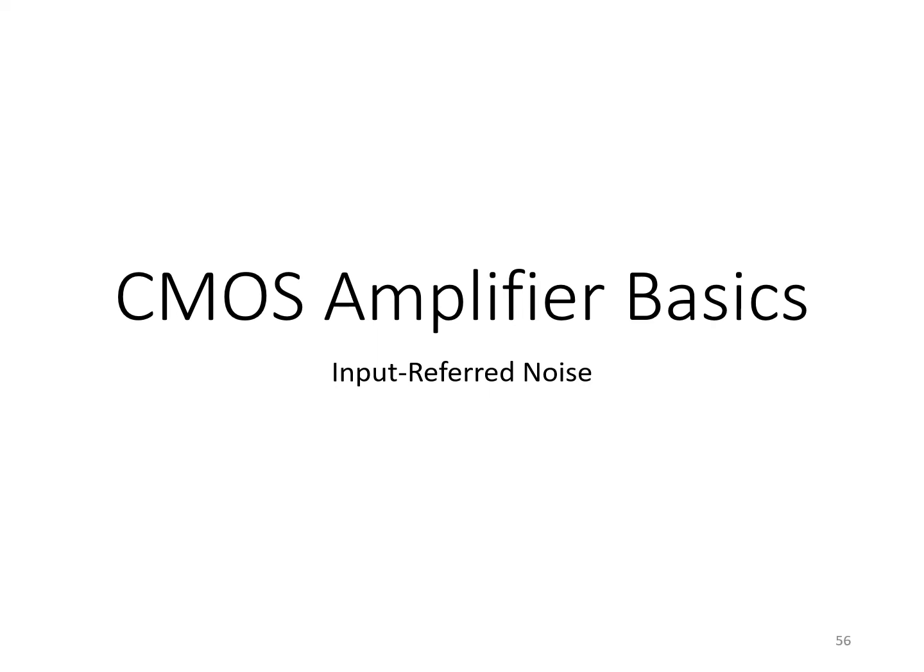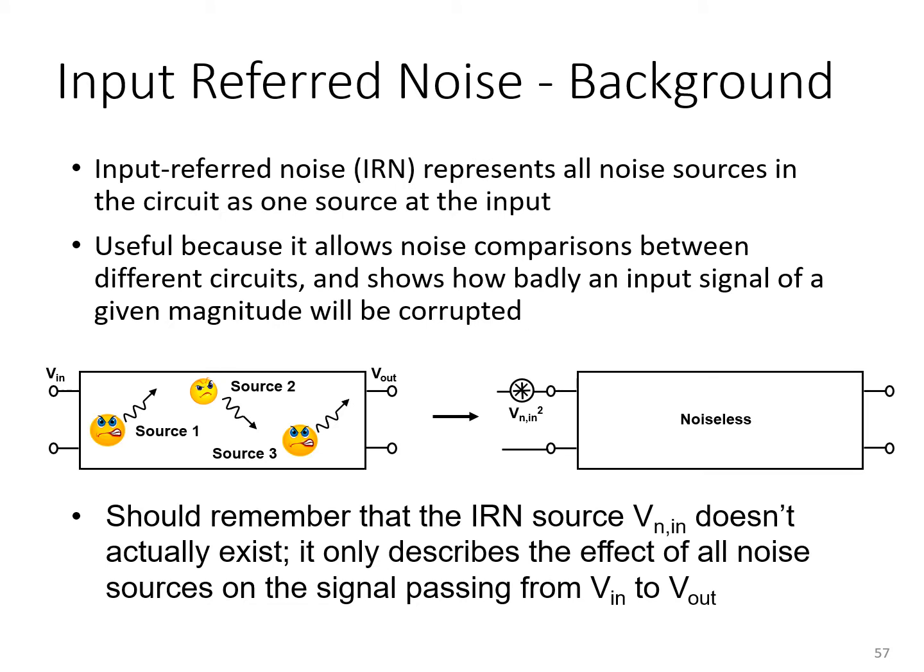This is just a short video about the basics of input-referred noise. We often quantify the noise of a circuit in terms of its input-referred noise. It's a quantity that represents all the noise sources in the circuit as one or sometimes two sources at the input. So the idea is you have a real circuit filled with noise arising from each and every component in